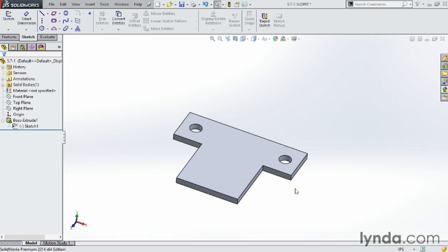Building good construction geometry is the single best way to make better sketches and to leverage the power of the parametric capabilities of SolidWorks. Always try to think through how your sketch will behave and try to minimize the excess dimensions.